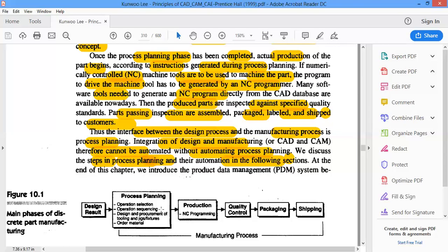Those rings have to be inserted exactly in those particular slots. Then the small end bearing should be placed at the other end of the piston with the piston pin, and then this assembly goes into the engine. So there is this sequence of operations.